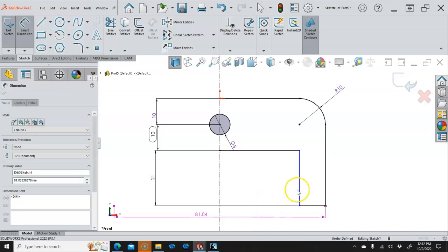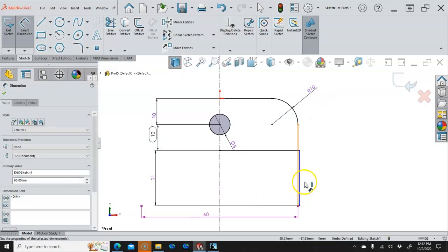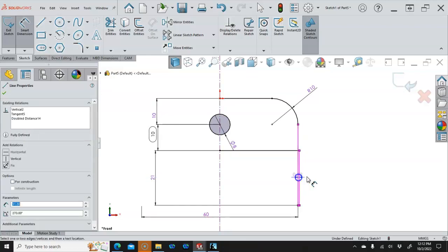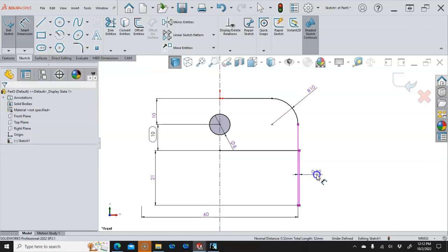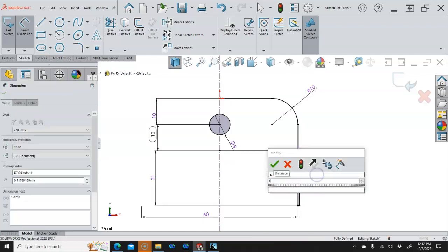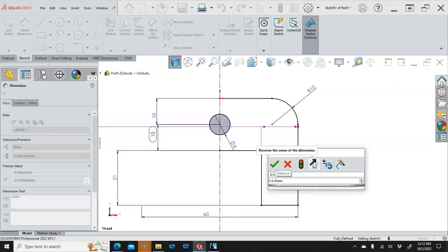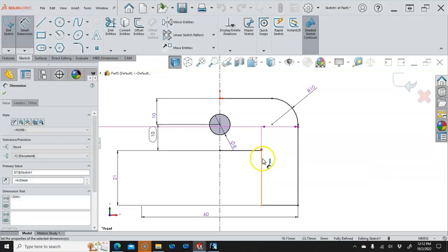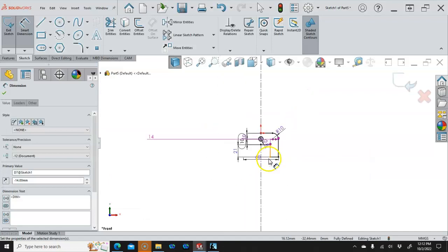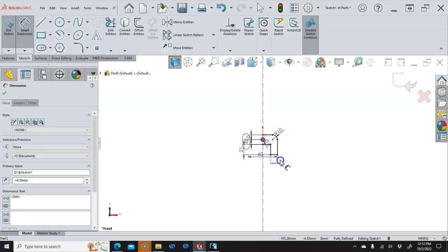And then our width is 14. So this is one of those cases where it got a little weird on the move, but I'm going to go ahead and apply it so we can put the 14 in there. And then I want to reverse the sense before I accept it. And this is one of the few places that you'll see a minus sign. Go ahead and accept it. When it applies it, it will still be a positive even though it threw it way out here.